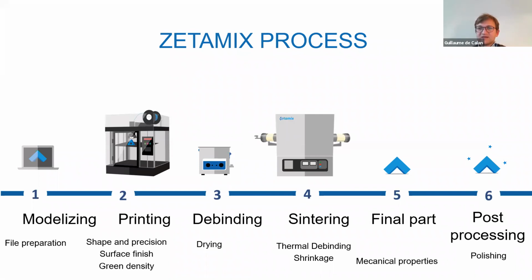The first thing is some of these infills are completely anisotropic. That means if you make honeycombs, for instance, the mechanical strength of the infill in X, Y, and Z is going to be very different. So that's something to keep in mind. Another thing is, and here we're really talking about very fine tuning, if you do a big part, you may have a slight impact on shrinkage also. So that's why we like gyroid, because it's almost the only infill pattern which is isotropic in 3 directions.